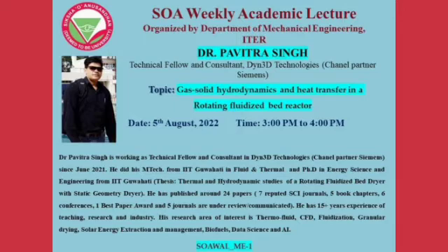So actually this is the simulation model of this RF-BHE reactor. So you can see a finite volume method is used, and the formulation used is first order implicit for the unsteady, and discretization of convection fluxes is first order upwind, and this is actually a three-dimensional model, and the phase coupled SIMPLE algorithm is used. This is given by Vasquez and Ivanov in 2000.